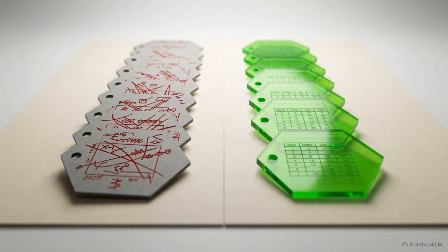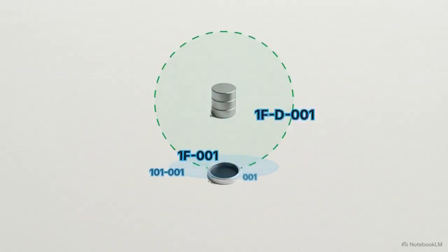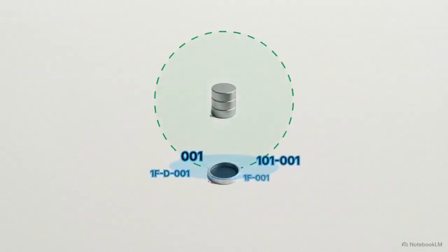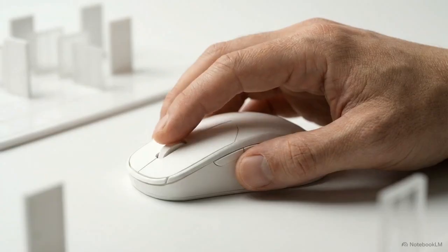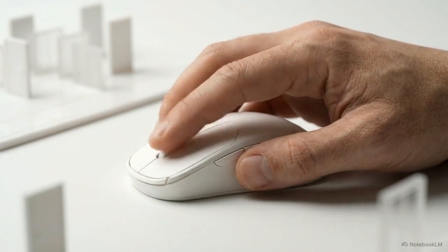This data table graphic highlights your ultimate failsafe. Compare the current number column against the new number column. You can verify exactly how the tags will change before committing the action. At this exact moment, your live Revit database remains completely untouched. 0 changes have been permanently written. Review the projected logic. Once the sequence perfectly matches your expectations, strike the Apply button to commit the data.